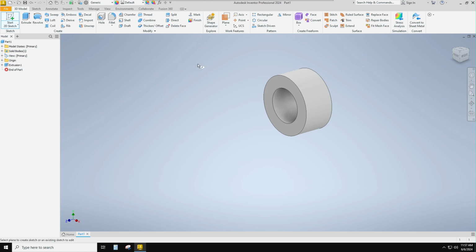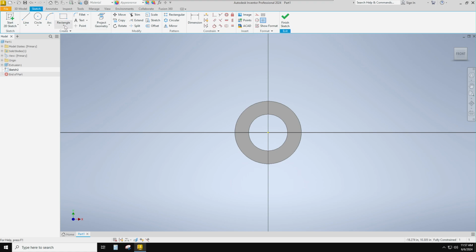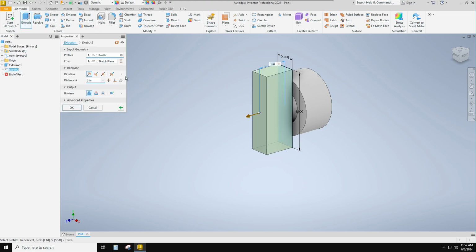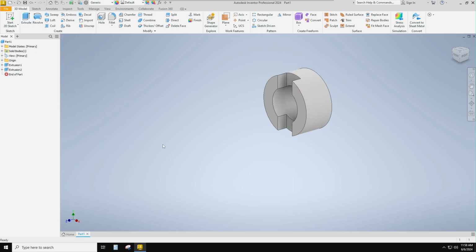And then on this front face, I'm going to cut a piece out. And I can do rectangles. Look, I can do this rectangle. I can make it 2 inches wide. Tab gets me to the other one. Oh, and it can be as long as I want. And it's going to extrude back in the other direction by 1 inch. There, look, isn't that cool?